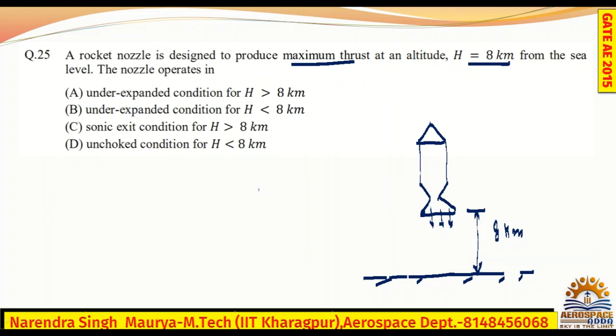The nozzle operates in under expanded condition for h greater than 8 kilometer, under expanded condition for h less than 8 kilometer, sonic exit condition for h greater than 8 kilometer, unchoked condition for h less than 8 kilometer.